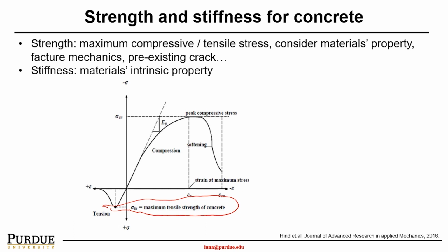In general, concrete will have a very, very small deformation. The strain at the maximum stress is typically smaller than 30 microstrain. So it's very difficult to determine the Young's modulus of concrete. The general rule of thumb in the industry is to use what is called the secant modulus.